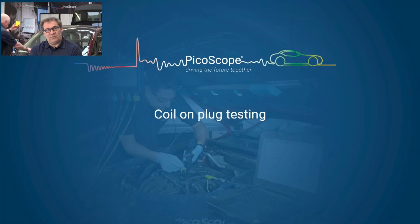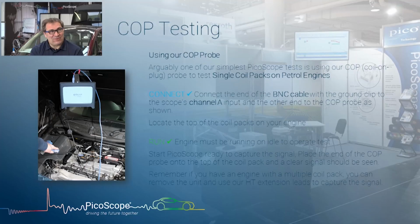Okay, so we're going to return back now. We're going to look at ignition. Actually, we did just see that in the relative compression, our coil on plug probe. So again, we've got a single channel being used, so we're going to use channel A with a coil on plug probe. In terms of connecting, simple as that, we plug it in and we literally locate the top of the coil pack and we place the coil on plug probe on the top.